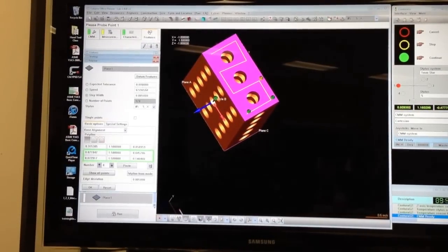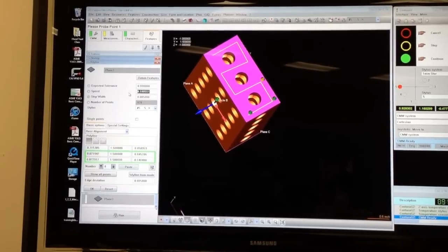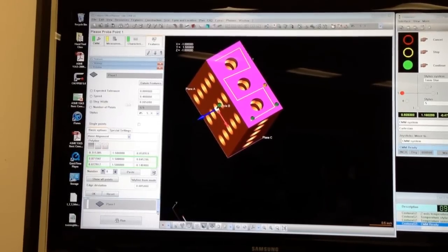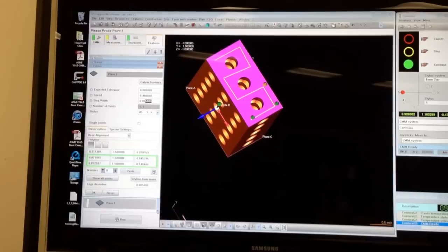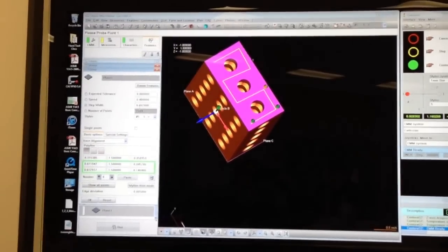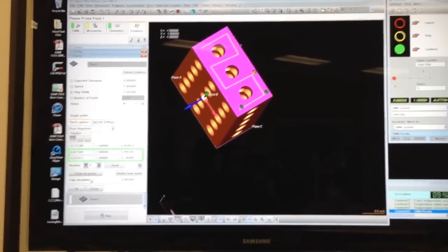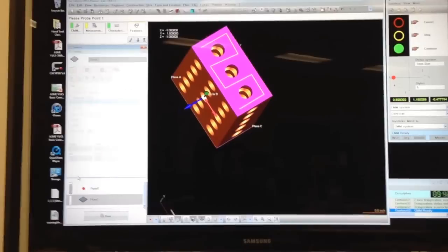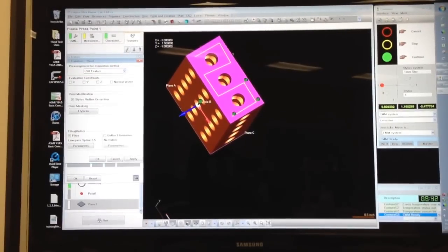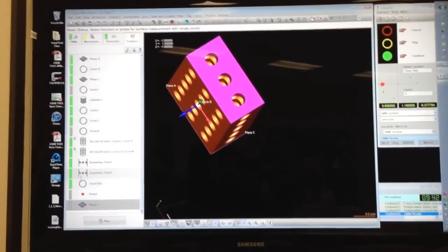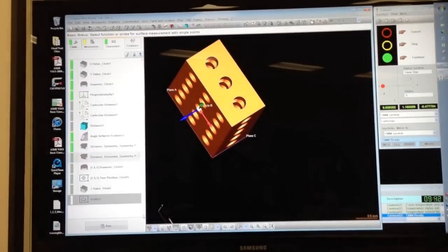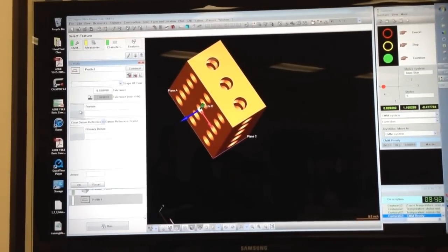There's our polyline. And once again, up top, I'm going to use 480, double my maximum accuracy speed. And because I'm measuring a tight tolerance profile, I'm going to drop my step width down to the minimum step width without taking special precautions, which is 2/1000ths of an inch. I'm going to click OK. When we scan, we filter, and when we filter, the default setting is always correct. Click OK. And finally, I'm going to come up here, Form and Location, Profile, open that profile up.